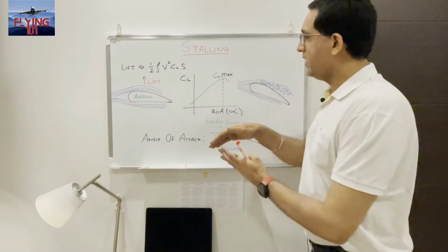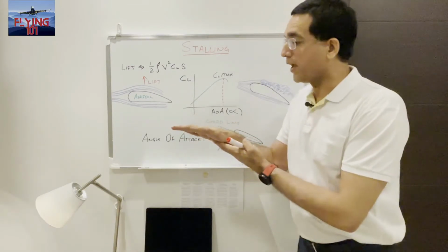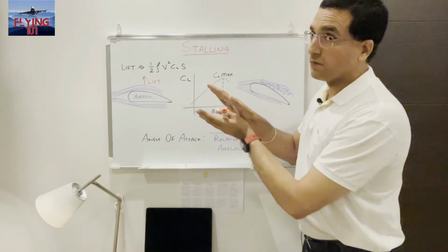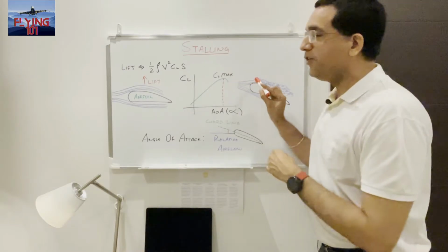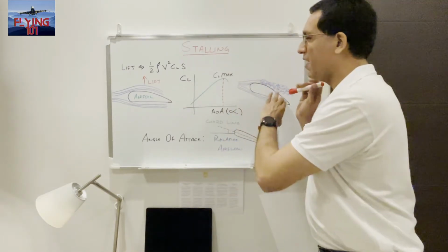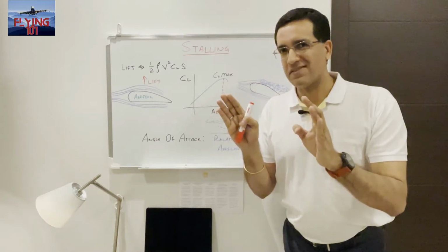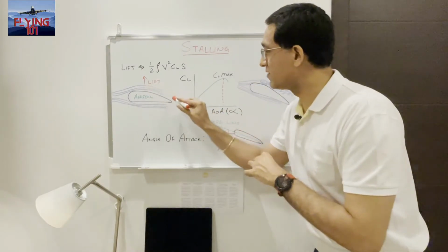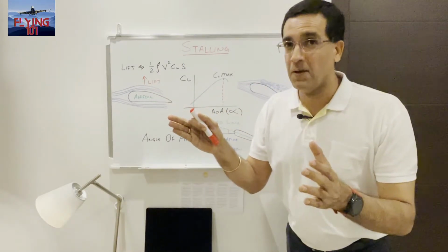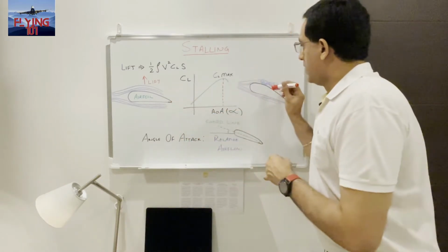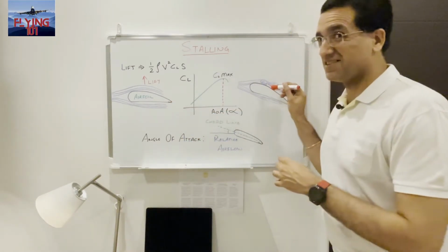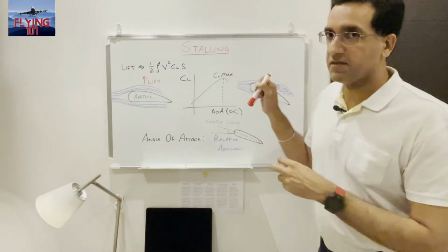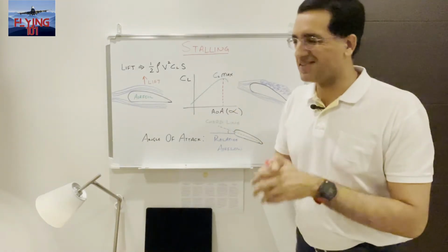Now what happens is, as the airfoil or the wing is being increased in terms of the angle that it's making with the relative airflow, it reaches a point where this smooth airflow no longer happens. It no longer sustains. We've then got the separation of the smooth airflow, or the laminar airflow, or the boundary, and it now becomes turbulent and disturbed, represented by these blue scribbly lines over here. Once again, forgive my drawings.